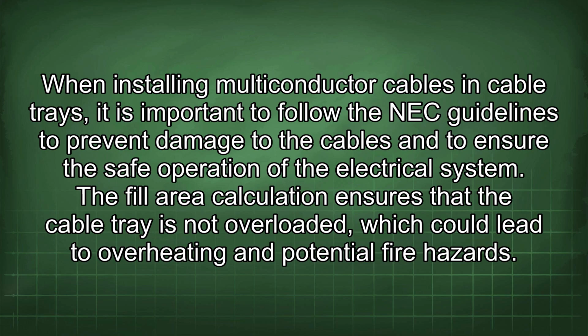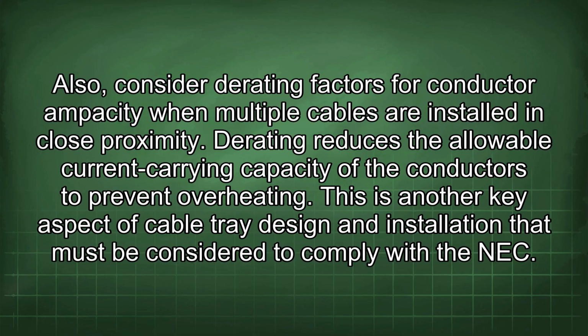The fill area calculation ensures that the cable tray is not overloaded, which could lead to overheating and potential fire hazards. Also, consider derating factors for conductor ampacity when multiple cables are installed in close proximity. Derating reduces the allowable current carrying capacity of the conductors to prevent overheating. This is another key aspect of cable tray design and installation that must be considered to comply with the NEC.